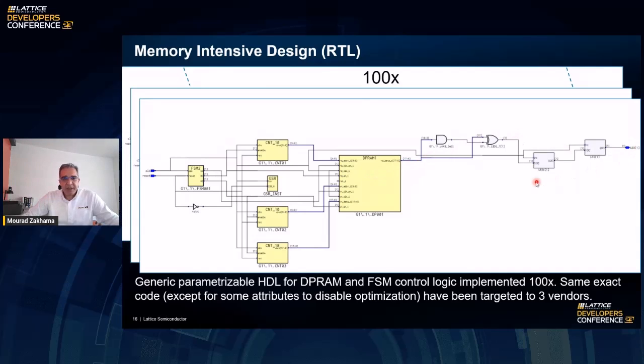So the memory has been defined in source code, not using any primitives from any vendor, and it's inferred by the synthesis tool to the primitive block for each vendor. It's a parameterizable design, and we have replicated that 100 times in each one of the three vendors.